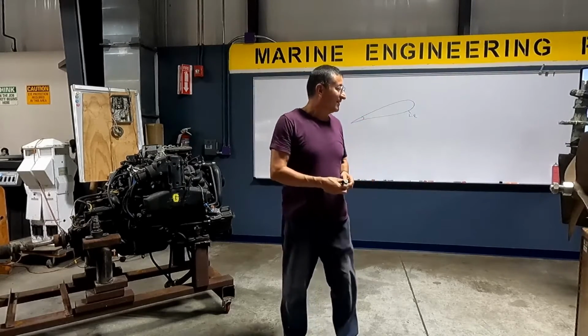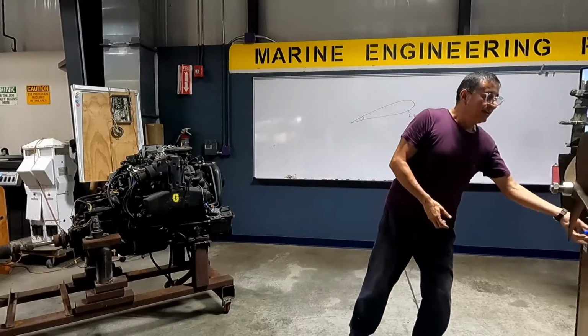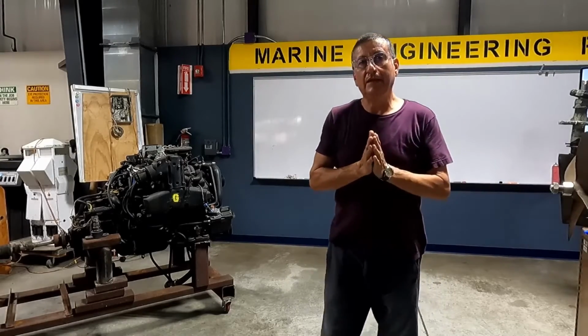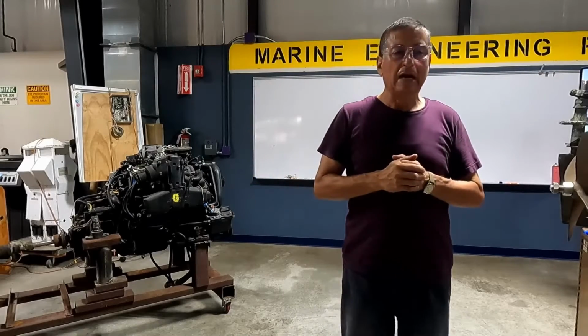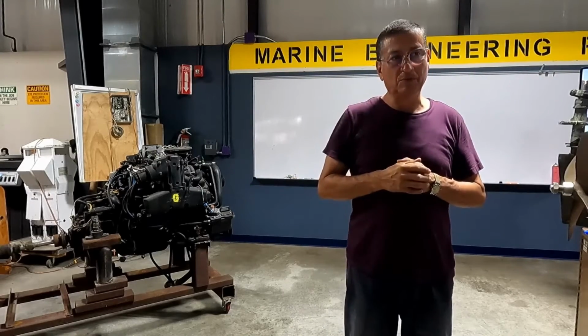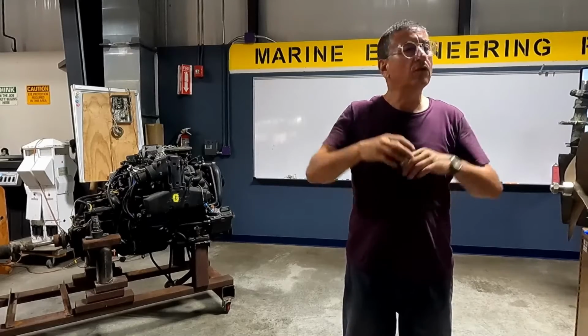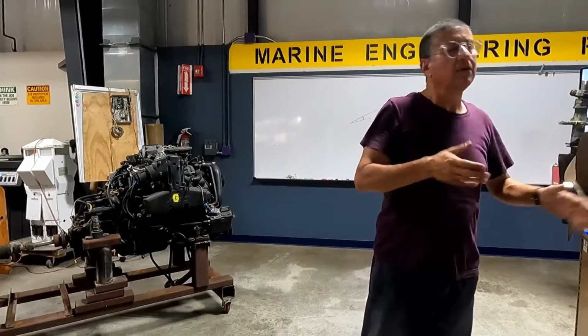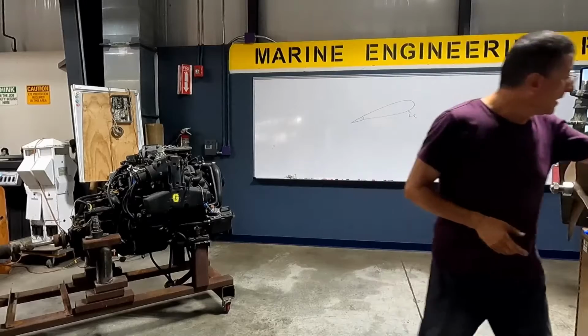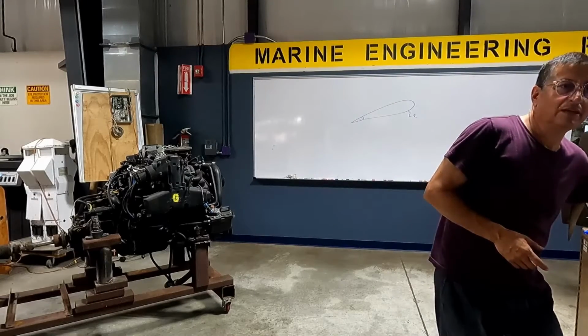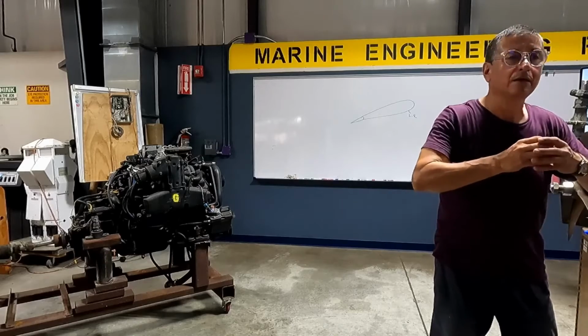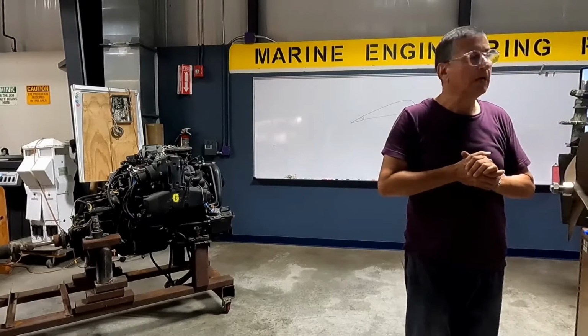Dangerous. Okay, great. Yeah, this is the history about the frequency. There are a lot of possibilities for vibration. And it's a common complaint of the customer, a vibration in the boat for different reasons. Because the shaft, because the propeller, because the bearings here in the strut, internally, the bearings have too much play and produce vibration.